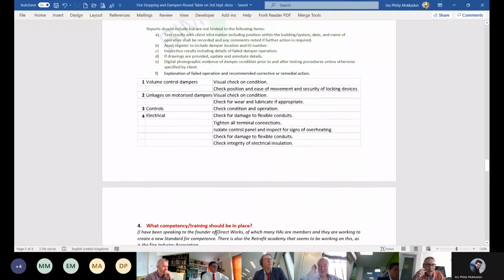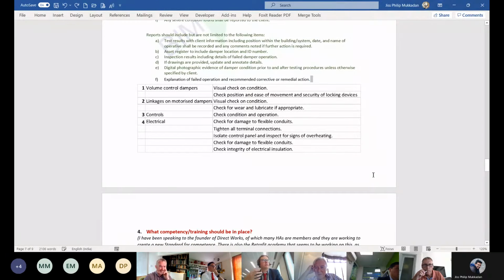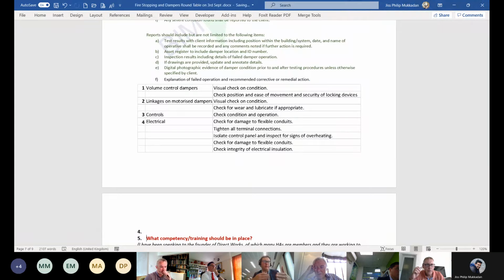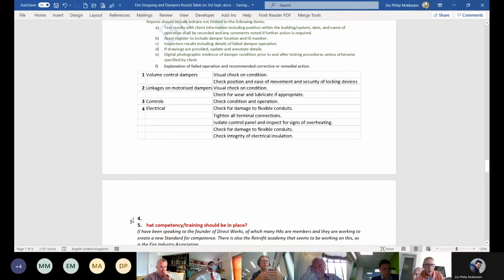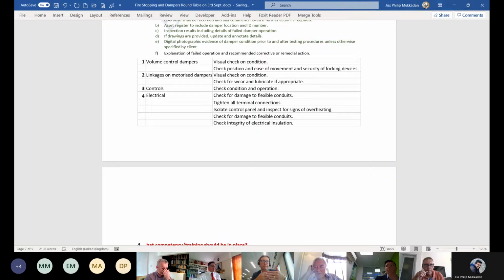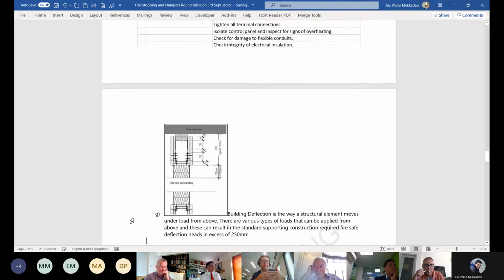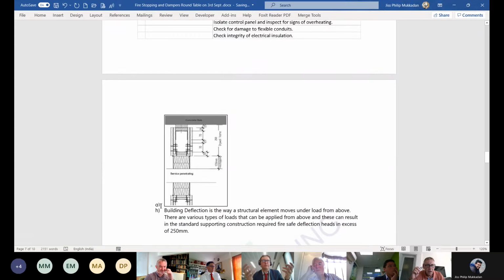Joel, I know I'm obviously late into the group. One of the things to consider, because I have to deal with procurement as well, and this is in the right context, I'm not throwing architecture under the bus. But architects do not design flexible walls. They do line and linear. So when you look at what you're saying in BIM, you'll get a block, and you don't know whether it's 2 layers of board and a 70mm stud. The problem is things like dampers and ductwork rely on the thickness, the aperture thickness, and the layers of board within that wall for their fire testing to be correct when you install it on site, because you've got to install as in practice as tested.